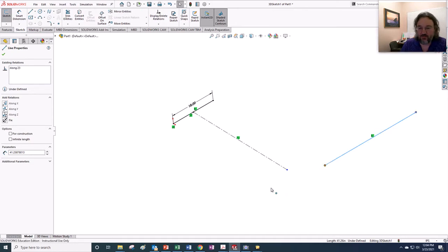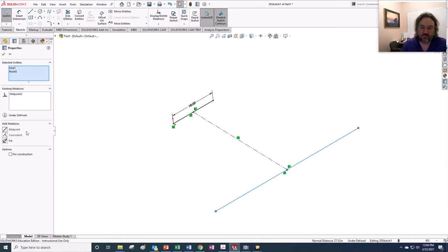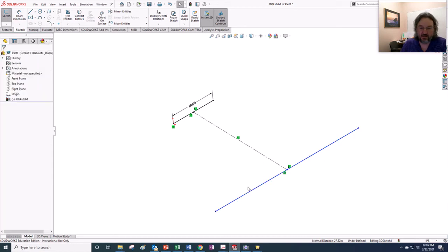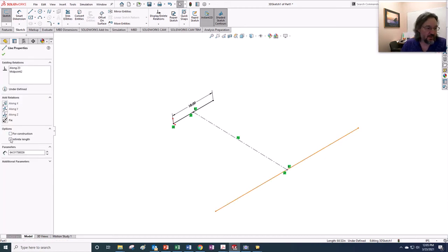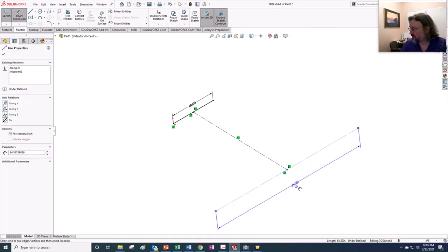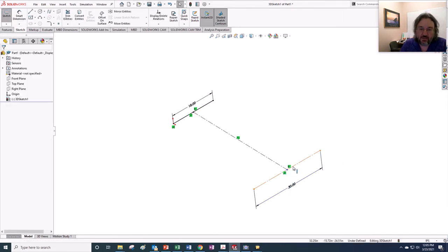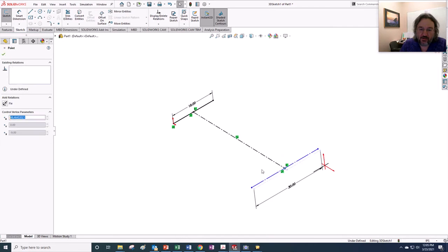And you see how far off I was. I thought I was drawing it in the Z direction, but I wasn't. That's one of the things you have to be really careful with. Let me put this guy on the center point of that, the midpoint. There you go. And oh yeah, he's still a solid line. I want to make this one for construction, and I'm going to make the dimension for A 2.5 feet, and so that's 24 plus 6, so it's 30. Math. And we don't have a length yet right here. That's why it's still blue.